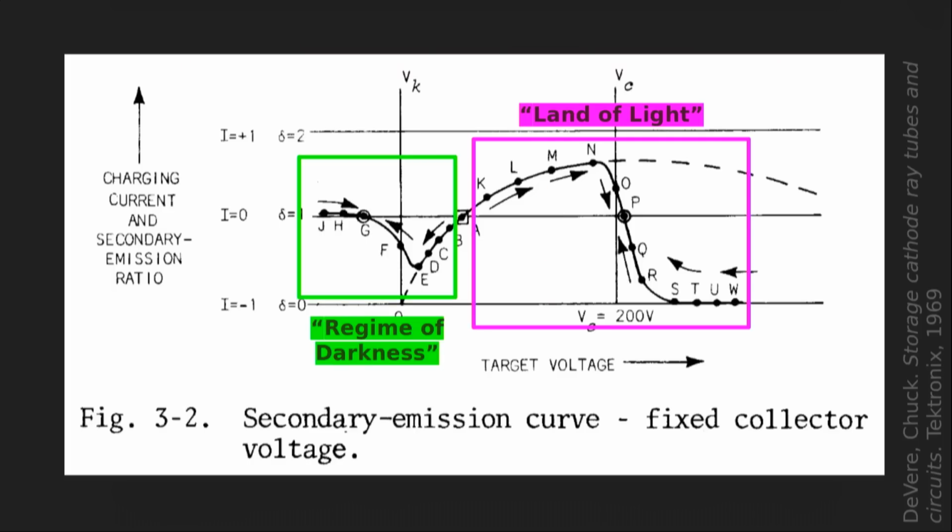There are 2 intervals of stability that can be achieved on any part of the faceplate. That's how storing works. That's why this is a bistable storage tube. Dark parts stay dark and light parts stay light. And because it's all happening on an insulator, those areas don't mix or move around. A dark patch on the screen can be immediately adjacent to a bright patch, and provided your screen is correctly calibrated, as Tektronix put it, remember they're an oscilloscope company, then they'll never mix.